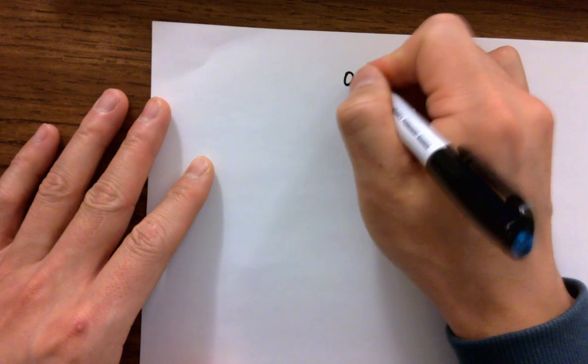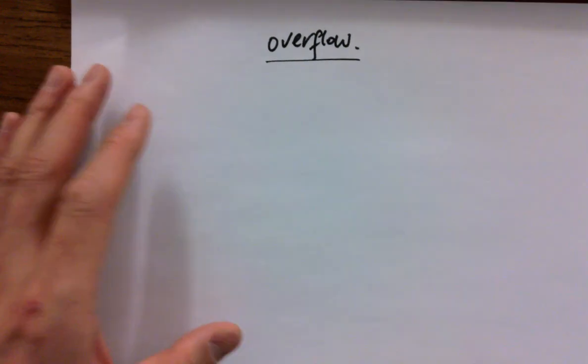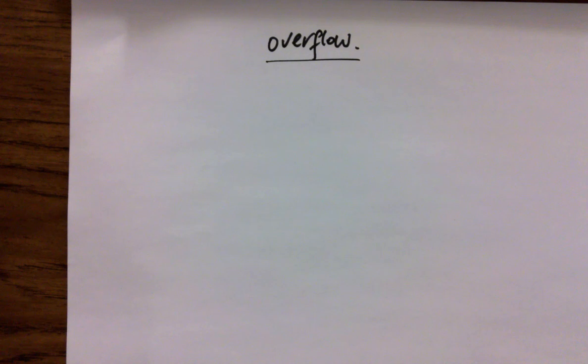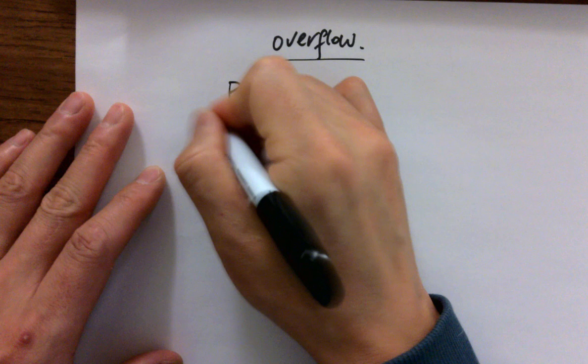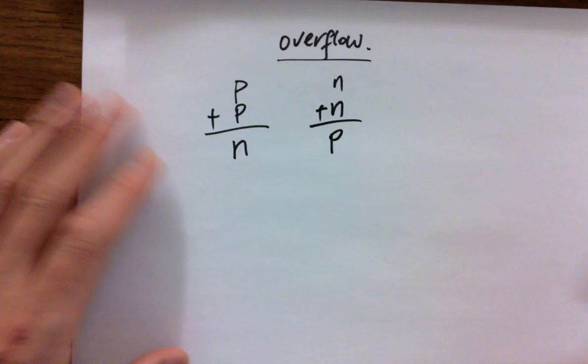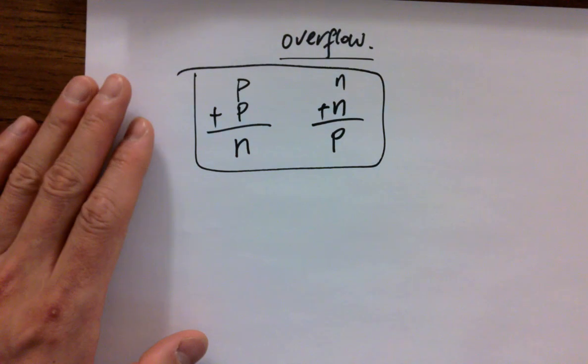And now let's do the binary calculations. There's a definition called overflow. This overflow is a little bit different from the overflow of C++ programming. Sometimes you get carry out, you call it overflow, right? But in here it's different, keep in mind. If I'm asking if there's an overflow happening for 2's complement calculations, you need to be able to figure that out. It's not carry out, keep in mind. Sometimes there's carry out, but it's not overflow in 2's complement. So overflow only happens when you have p plus p and you're getting an n, or n plus n, you're getting a p. Keep in mind that's only 2 cases for the overflow in 2's complement.